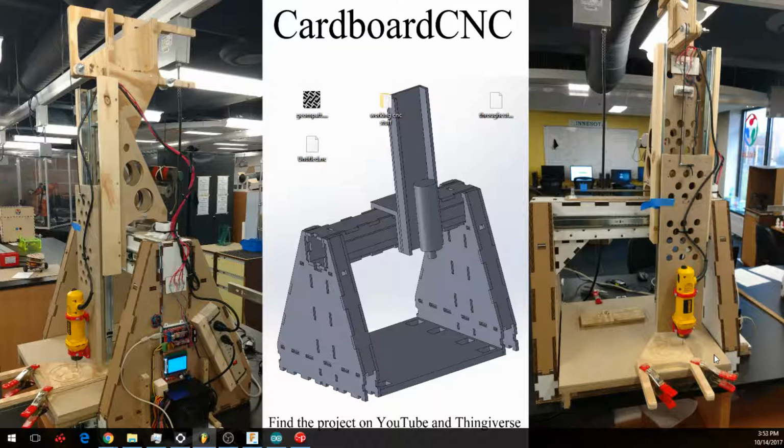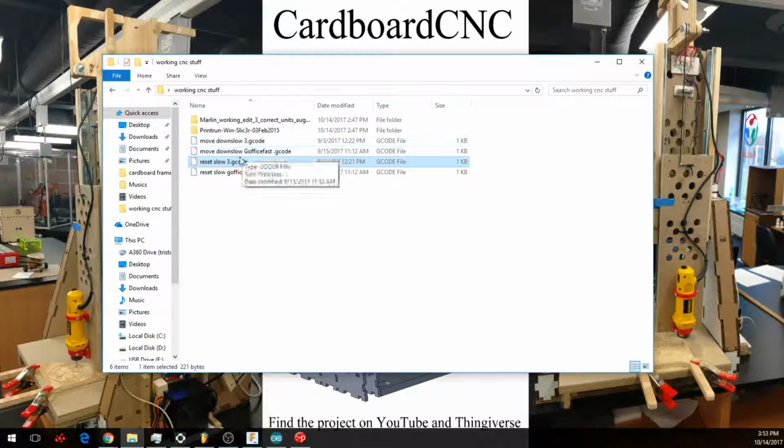It's actually more in the corner, 1 inch away from all of the walls and 1 inch off of the build plate. I'm doing that as a safety factor, because if it ever loses a step, it won't try to run into the wall. So the first bit of code brings it down to the build plate.